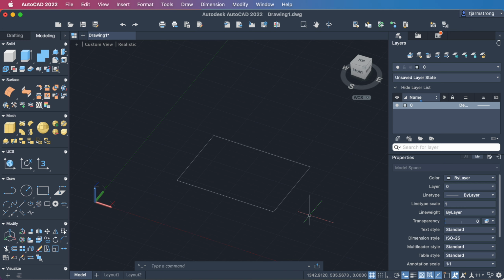So the next thing I do is create my sides, and I'll do that using the extrude command. I'm going to type extrude, and actually I should probably point out while I'm doing this, that if I use the default, which is solid, I'll make a solid box like we just saw in the previous example, and then I could change the shape and I could use explode to take it apart. But in this case I'm going to do it just slightly different.